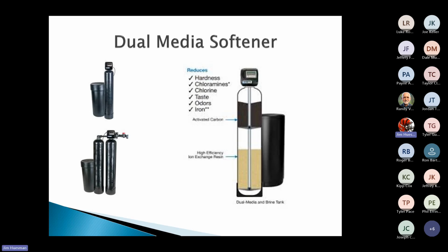So now to jump into something a little bit new. I'm getting a lot of questions on our dual media. So now we have dual media, and it looks just like a softener. It's set up just like a softener, but now we've added a little bit of both worlds. So water, again, will enter down through our dip tube, through our base, up through our media, grabbing onto the calcium and magnesium.